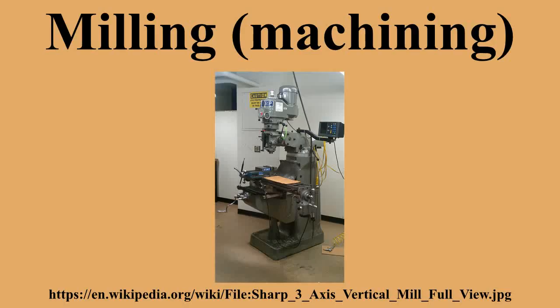A mill drill also typically raises and lowers the entire head, including motor, often on a dovetailed vertical, where a drill press motor remains stationary, while the arbor raises and lowers within a driving collar. Other differences that separate a mill drill from a drill press may be a fine-tuning adjustment for the Z-axis, a more precise depth stop, the capability to lock the X, Y, Z axis, and often a system of tilting the head of the entire vertical column and powerhead assembly to allow angled cutting.